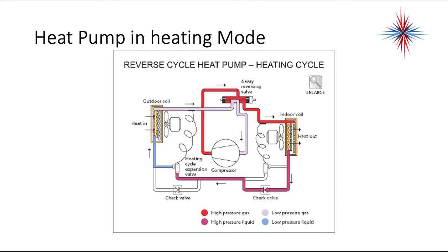Okay, so we have our compressor. Our compressor is discharging through the discharge line to the center. Again, because it only connects to two spots, it goes to the indoor coil because this has now slid over. This is a little slide part that we talked about in a prior reversing valve video. So now the indoor coil is my condenser.